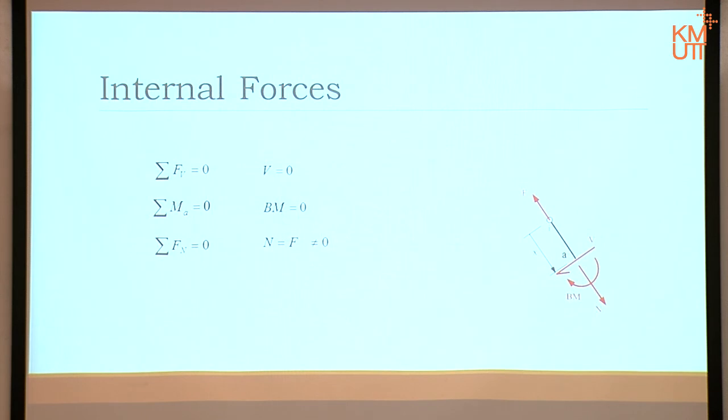This proof shows that if all connections are pin joints, including the supports being pin type, and there is no force acting on a member, only acting on the joint, there will be only axial force inside the member, which reduces our unknowns. Every single member, rather than having 3 unknowns changing with point, has only 1 axial force per member.